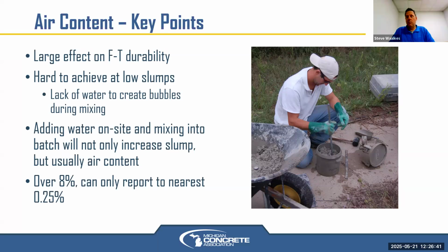When you do an air pressure meter test, you're pressurizing it up to 14.5 psi and then releasing that pressure. I know the gauge doesn't show that; it just shows initial pressure, and not in psi. But at any rate, the super air meter does that, and then it does it to 30 psi and then 45 psi, and then you release it back down and do it again, and you measure the difference between those 2 curves at 14.5, 30, and 45.